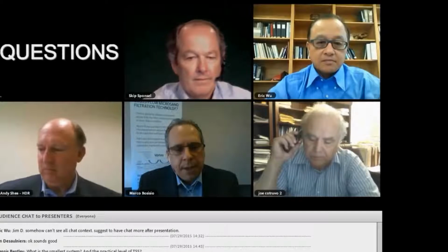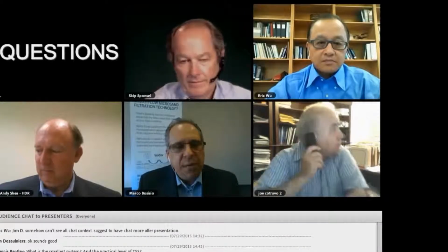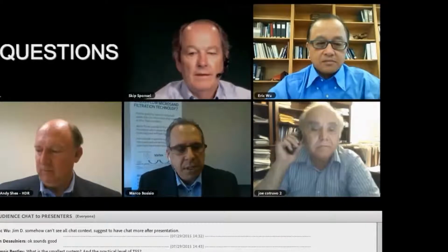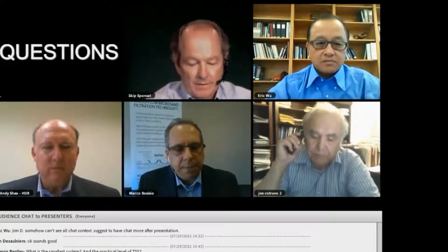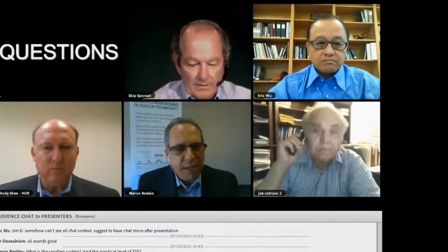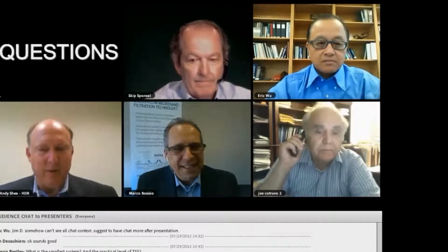So we do have to top up some of the sand probably once per year, or once every 6 months, making sure that there is always microsand on top. Designers know that we need to add some sand from time to time to media filters, so it's pretty much the same as other filters. Did I answer your question? Yeah, no, that's great. Appreciate that.